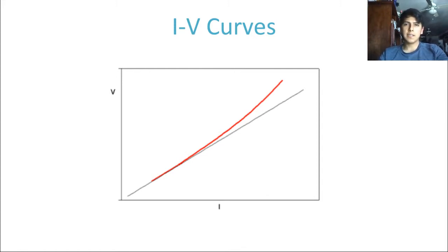When current is passing through it, the material is heated by the Joule effect, and its resistance will vary accordingly, so that for the same voltage applied, the intensity will be different from what would correspond if the temperature remained constant. The measurement in this case must be carried out quickly to avoid the variation of the resistance with the temperature.